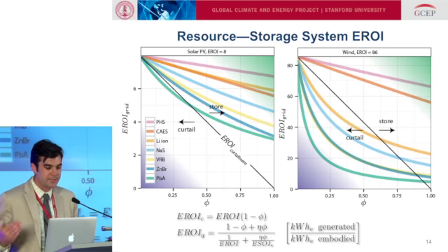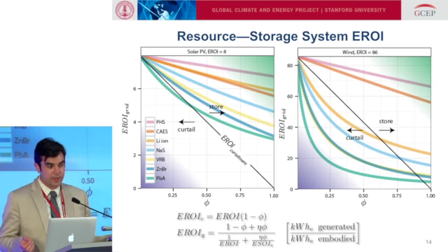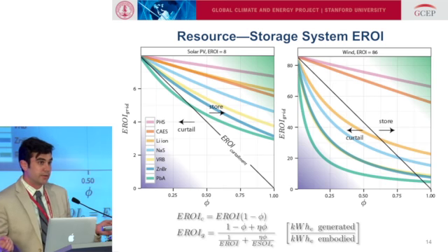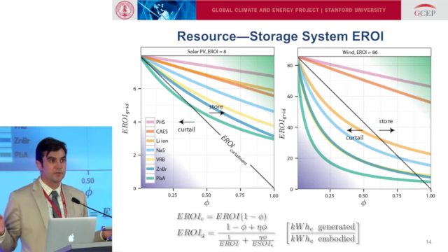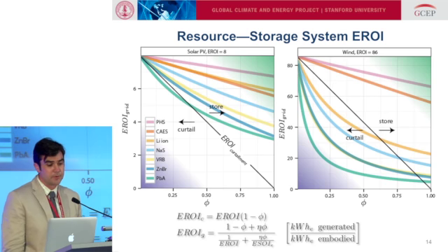And so it behaves the way resistors do in a parallel circuit. And so as the fraction that goes through storage increases, the weight of the EROI value and the ESOI value become comparable, such that the grid scale EROI will be bottlenecked by the smaller of those values. So the EROI grid for solar technologies, when it passes through storage, performs quite well when compared to the EROI for curtailment. This is because solar energy is energetically expensive.